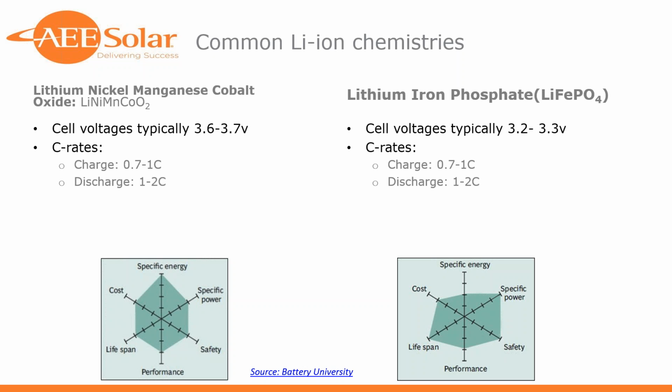If you've ever been to one of my trainings, you've heard me preach about the importance of going with a quality, name brand provider, making sure it's a brand you can trust and that they've done a good job on the battery management system. So the BMS is really going to be critical in our solar plus storage applications, where the inverter is going to be making decisions based off of either the voltage it sees off of that pack, or the instructions coming from the BMS that are going to tell the inverter the current state of charge, battery temperature, discharge rating, etc.